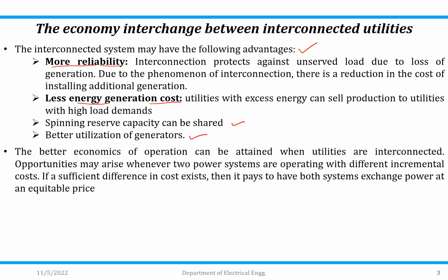Yes, definitely, opportunities may arise whenever two power systems are operating with different incremental costs. Incremental cost means the cost of generation, and already we have seen this. Whenever we talk about the cost of generation, the major part it includes is nothing but the fuel cost. If a sufficient difference in the cost exists, then it pays to have both systems exchange power at an equitable price.